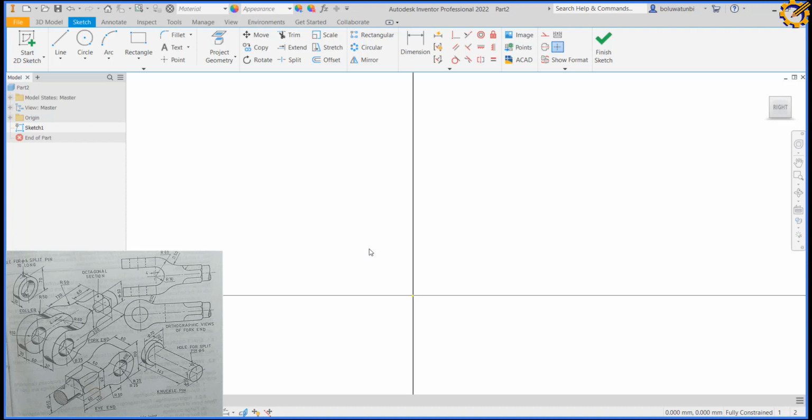So how do I do that? I'm going to first of all pick a line, draw it straight like this. I want to use the revolve tool. So picking this line, drawing it this way. Let me just draw, stopping somewhere. I haven't dimensioned that line yet. I am just drawing. Take note. Then close it.